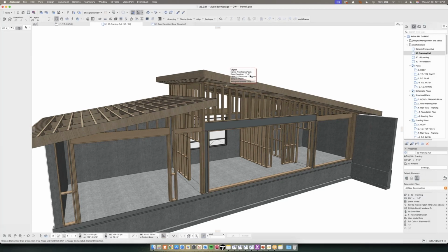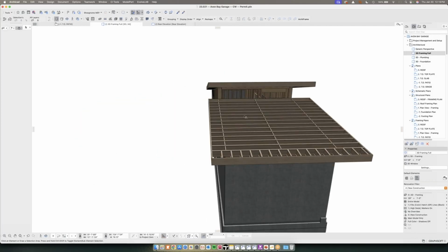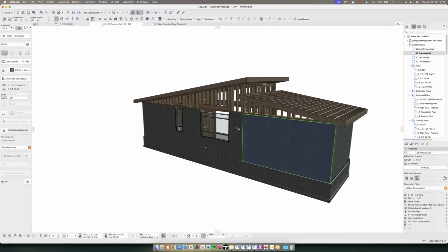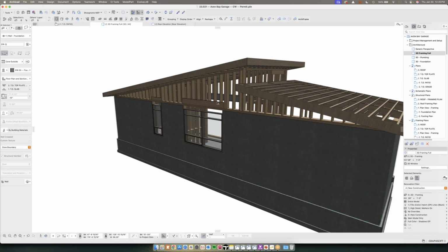I'll show in a little bit in the other project how it's really an advantage to use an ArchiFrame beam versus an Archicad beam in terms of documentation. But the ability to frame out these walls, show the lintels, see how the rear concrete walls actually interact, and we can frame the rake walls on top and build the lintels into those components, I think is really powerful.